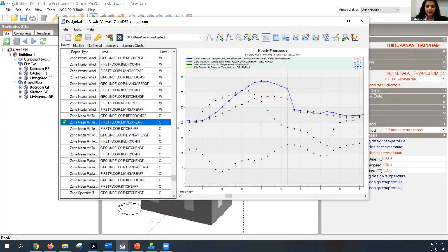Is it possible to factor in the effects of context buildings on the wind flow, heat influx through the envelope, etc.? Yes, certainly for heat. You remember I showed you the way that I drew that component block as a fly screen roof. In the same way, you can model surrounding buildings as component blocks, and they will provide all the sun shading, etc. Now the wind effects are a little bit more suspect. They're not that easy to model.